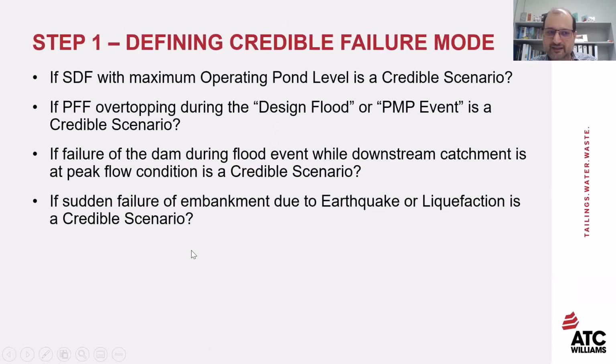Simulating the dam break. There are several steps that need to be followed to do a tailings dam break assessment and simulation. Step one would be defining the credible failure mode. We need to ask if a sunny day failure at the maximum operating pond level is a credible failure mode, or if a post-flood failure, overtopping during the design flood or the PMP event, is a credible scenario.